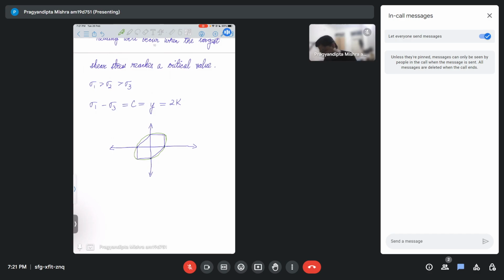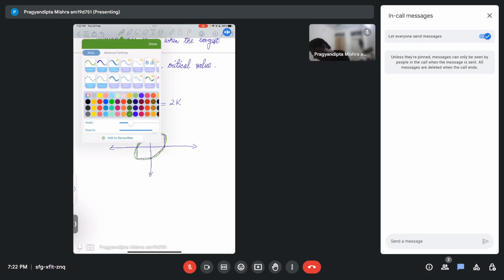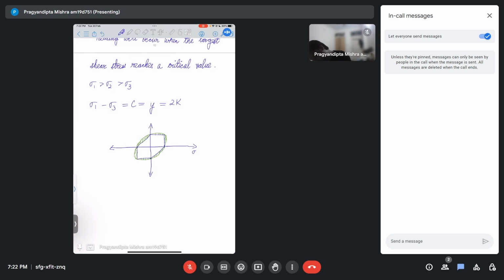So essentially you have this extra part, the green shaded region, which von Mises also takes into account while looking at yielding, while Tresca is encompassing a much smaller region. Say this is sigma A and sigma B, the biaxial stresses, and these are all yield. This is Y, this is also Y, this is also Y. Negative, let's say this is negative. So your von Mises criterion is encompassing a much larger area compared to Tresca.